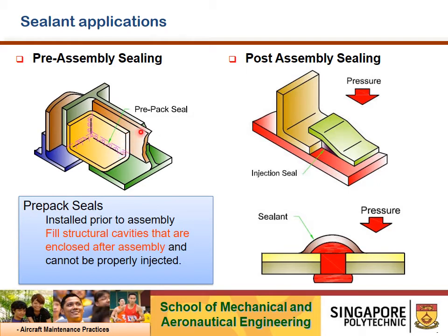Okay. So the other one would be a sealant over the fasteners. This will actually prevent moisture from getting into the fastener installation, or any fumes or escape of pressurization air from the aircraft structure. Alright, so this will give you a proper sealing effect.